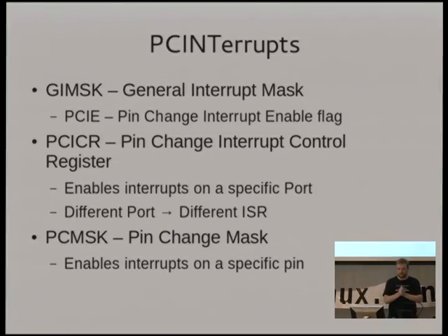The earlier that the chip can decide not to deal with an interrupt, the less power and the less effort the chip is going to use. So if you have a whole bunch of things, buttons say, that might cause interrupts, and you group them all on the same port, that means you can turn off all the interrupt handling for the other ports. So there's no monitoring of that at all while the chip's in a sleep state.